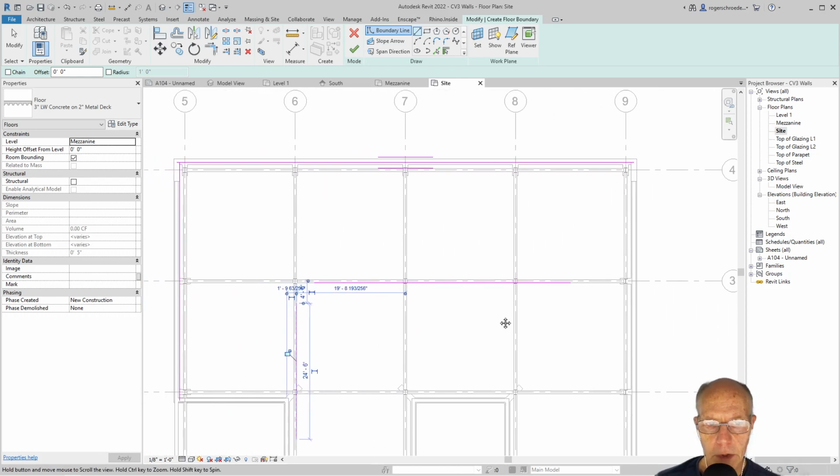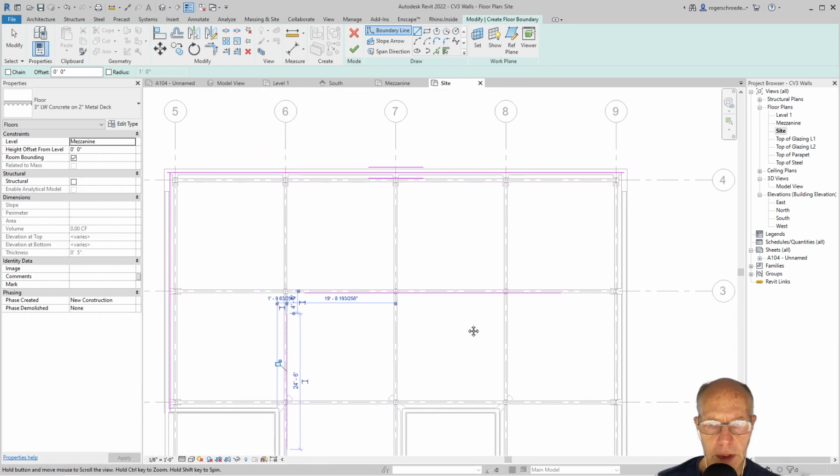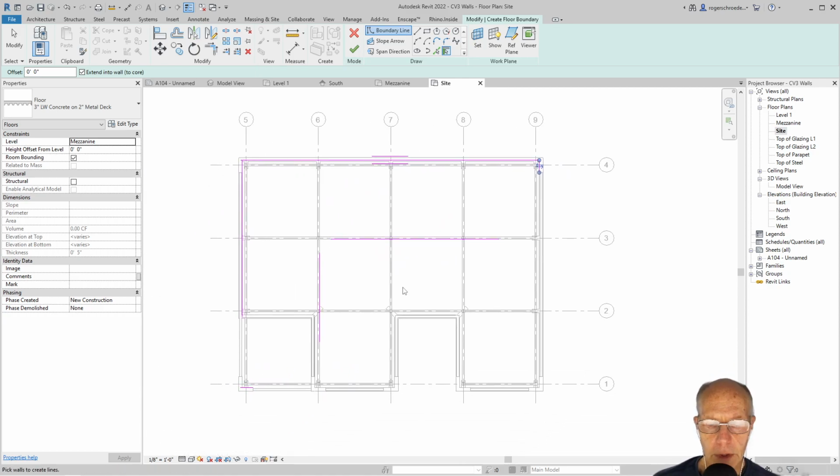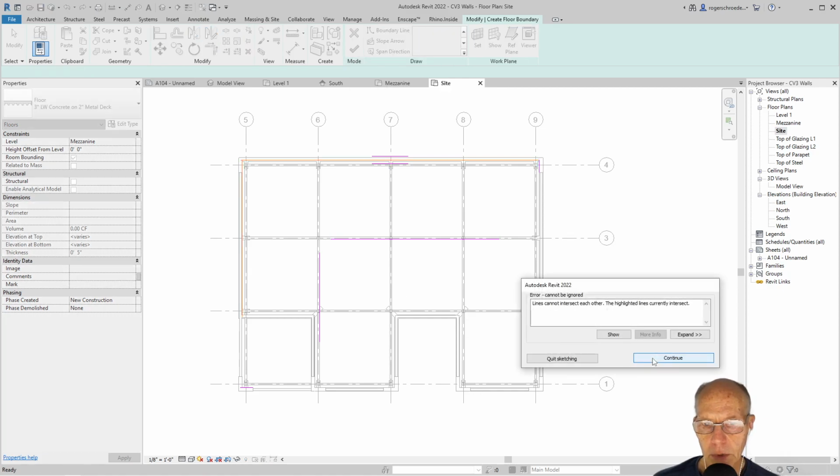And we need another surface over on this side, and I'm going to use the Pick Walls tool, this little icon here, and connect that. Now, I've got all of the things that define the perimeter, but they're not all completely connected to each other. And if I was to click complete, I'd get all of these orange arrows telling me places where things aren't connected. And so I'm going to go continue.